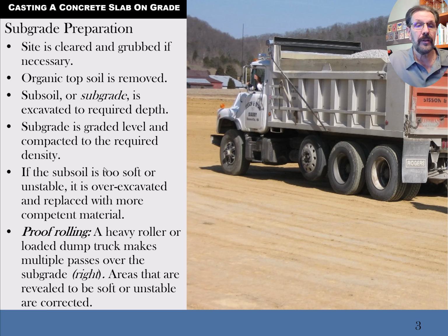Here they're preparing the grade. If you're talking about a slab on grade, you've got to have really good ground because it's being supported by the ground. Often there's hardly any reinforcing on many buildings in the concrete slab. It's supported by the ground. They'll often put some mesh in there, but as my dad said, as a structural engineer, he would say that you should tie a rope on that mesh so you can pull it out and use it for the next job afterwards too. In other words, what he was getting at is that this mesh is not going to help keep that concrete from breaking or cracking. It's only going to hold the broken pieces together.